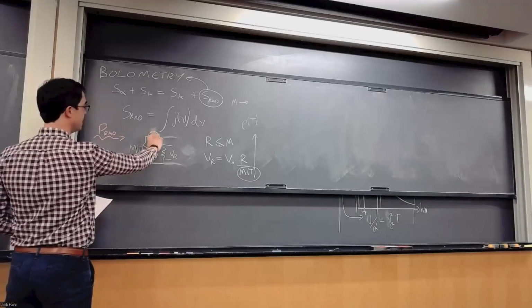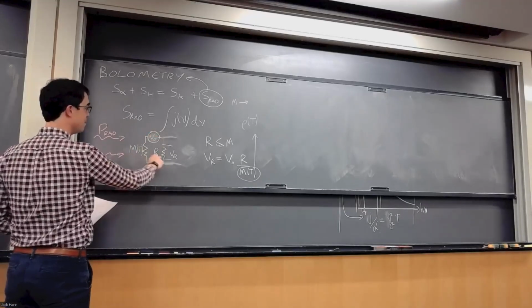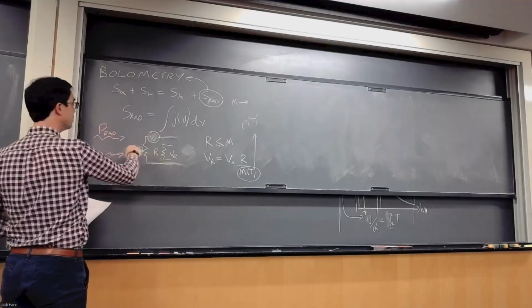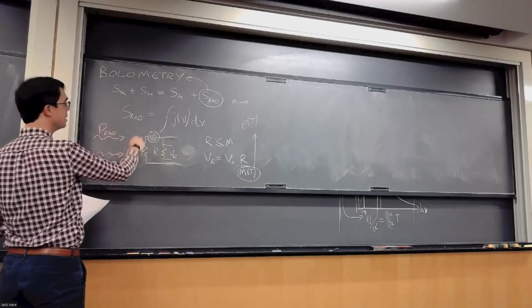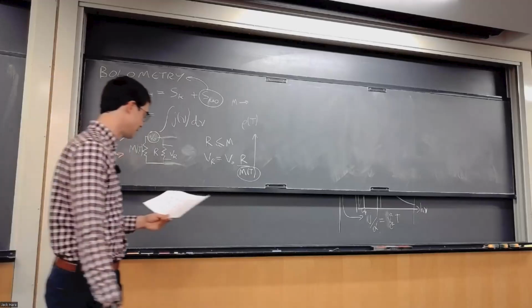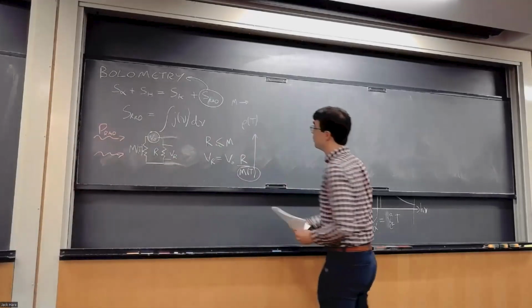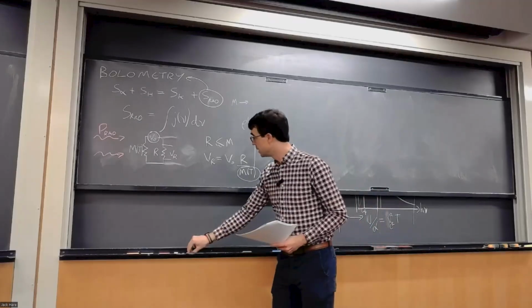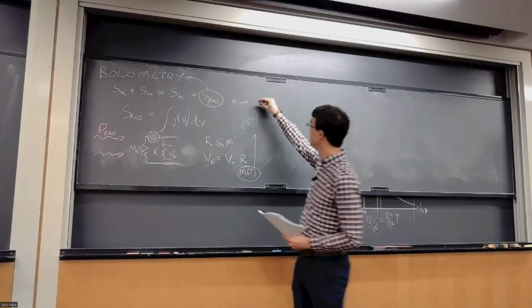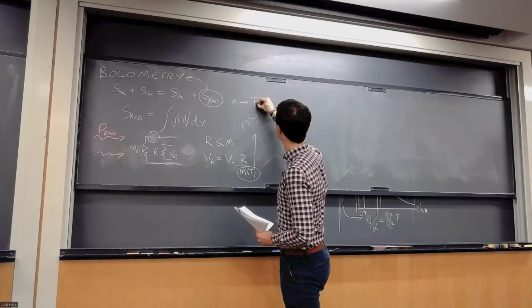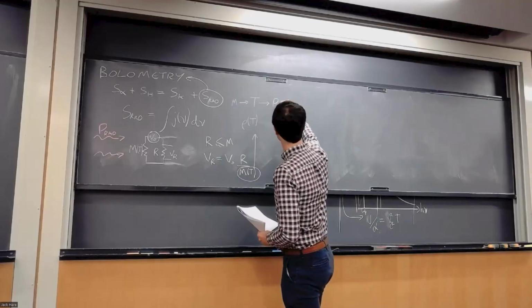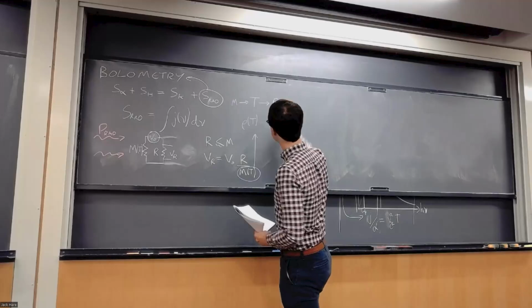Good, so it's a voltage divider. We're dividing V0 between M and R, and we're measuring the voltage across R, which then of course tells us the voltage across M, which then tells us what resistance M has. So if we're measuring the resistance M, we can then use some table of ρ(T) to get out the temperature, and from that temperature, we can make an estimate of the radiation power incident upon it.